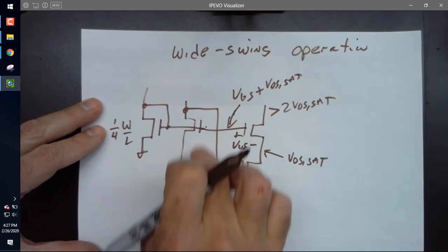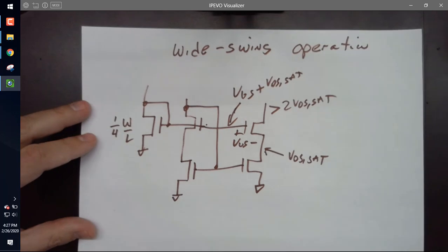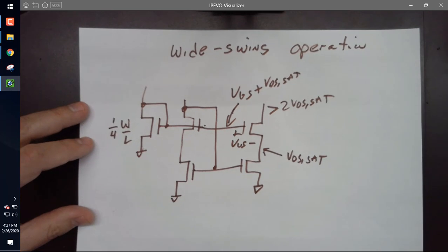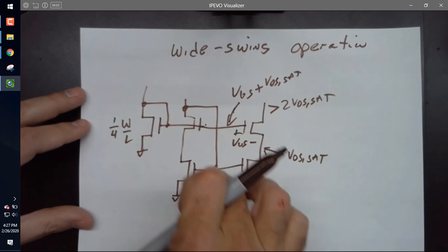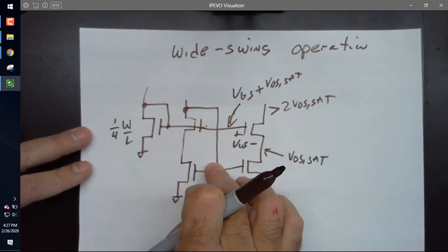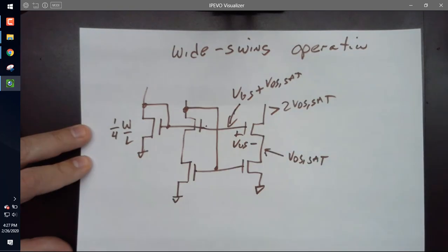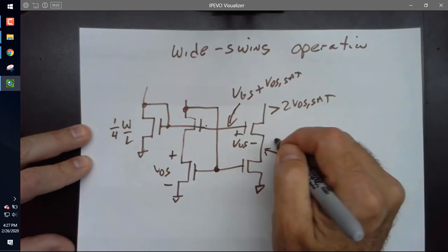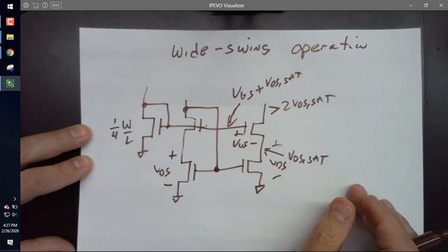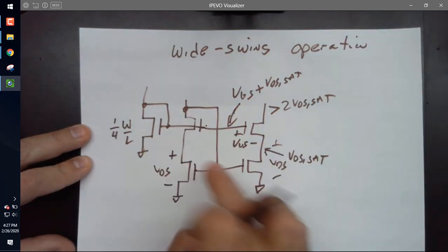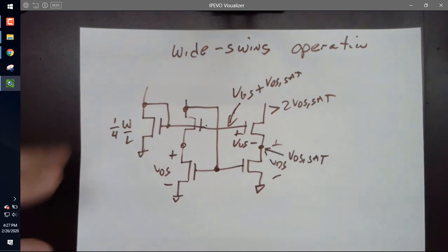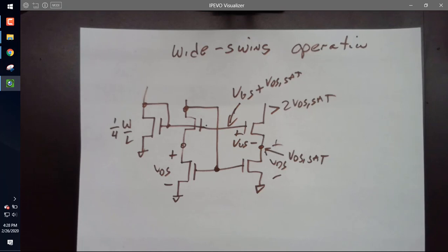And then I use, what do I use this device for? That was something we went over. Well, I could just connect, the first way I did it was I just connected this one, gate drain connected, right? So here I said I'm going to make it so the currents match better. And I'm going to do that by making this VDS the same as this VDS. And if I do that, I can add this device to do that so that this VDS matches this, because that VDS is the most important thing for matching. Everybody got that? All right, any questions?